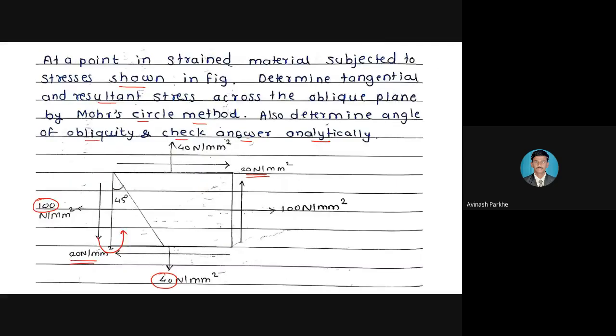If the shear stress rotates in anticlockwise direction with the major principal plane, or vertical plane, then that shear stress we have to represent in the negative region.